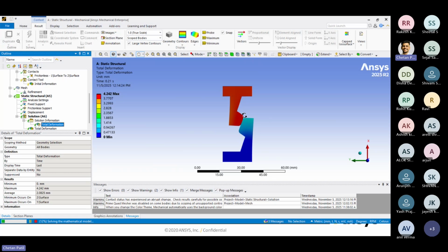So the major important parameters which affect your particular geometry and lead to penetrations are, first, your contact regions, the second is your mesh, and the third one is your load division. Load division is done in the analysis settings through the auto time stepping to be changed. This way you can particularly apply the conditions on the geometry. That is, the contact non-linearity can be applied over here.